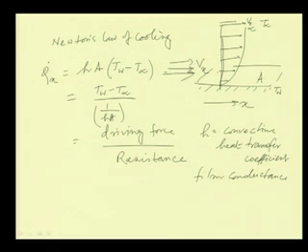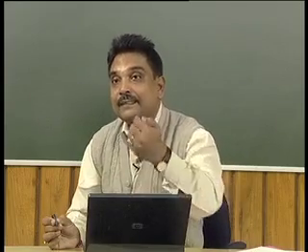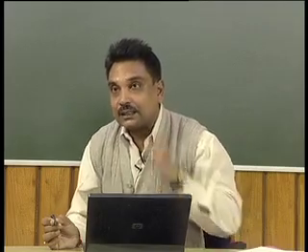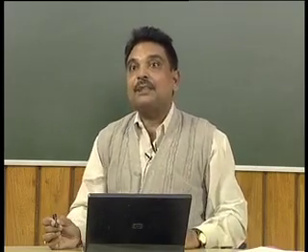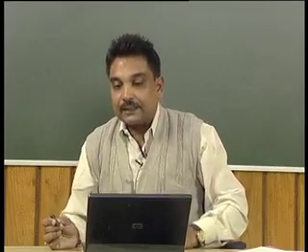and the resistance offered by the film is also taken care of by the inverse of this convective heat transfer coefficient h, and therefore, the heat is being transferred or conducted. Basically, what is happening is that for those fluid elements adhered to the surface of the plate, the heat transfer is taking place in the form of conduction through the film, and therefore, sometimes h is called film conductance.